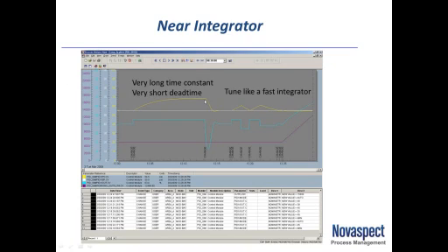If I had used the traditional conservative 3 times tau rule here, this loop would have a time constant of 10 minutes. It would take 40 minutes to come to steady state after a disturbance. With my integrating rules, my time constant is 15 seconds. I don't have a ratio anymore of automatic behavior to manual behavior is 3 times longer. I have it's 15 times faster.